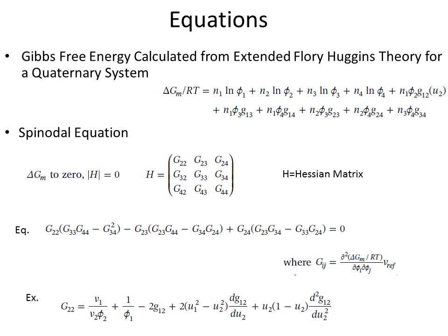So to put it a little more simply, the binodal curve represents the initiation of phase separation and is calculated by minimizing the free energy. The plait point is the point at which the binodal and spinodal curves meet. The exact location of the plait point signifies that the minimum point obtained by the calculation is the true minimum in the given range. The changes taking place during the phase inversion can be correlated with the corresponding change in free energy of the system.